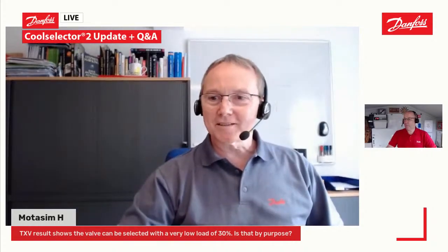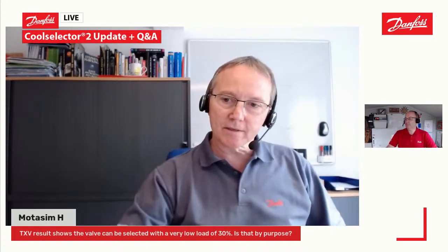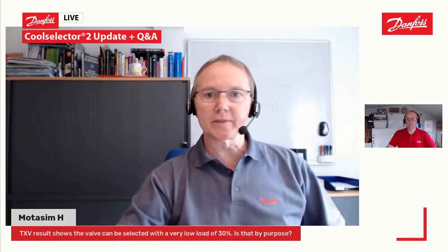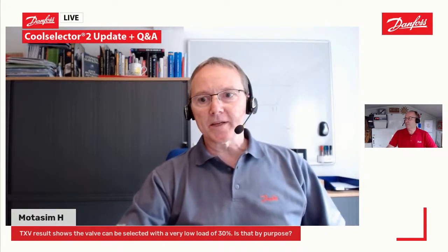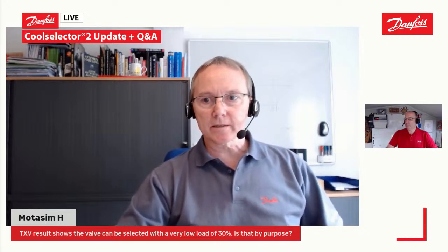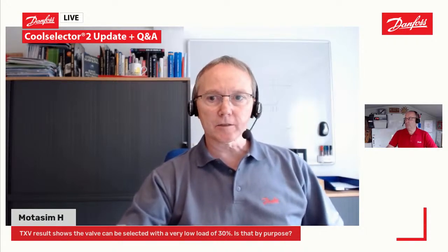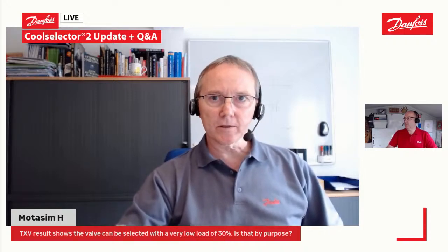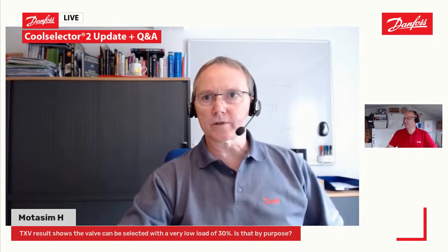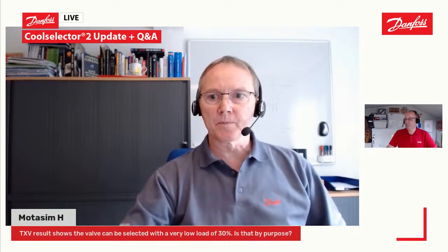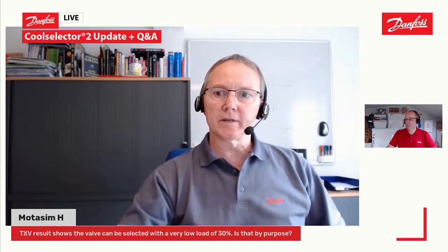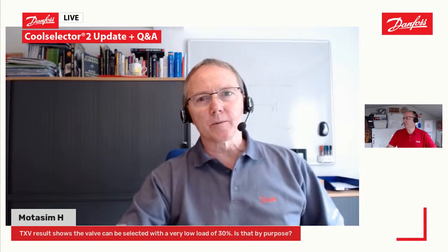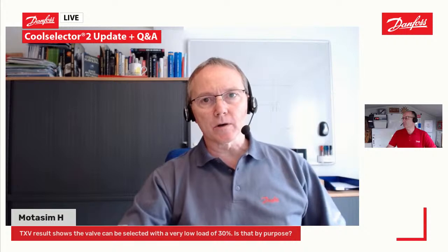Well, this is somehow because of the principle of dealing with calculation results in Coolselector. Basically, you should always select a TXV at 100% load. Doing that, you get the best results and you're on the safe side not to run into a hunting system, for instance. The 30% is coming because we want to support also with the information about low load possibilities.